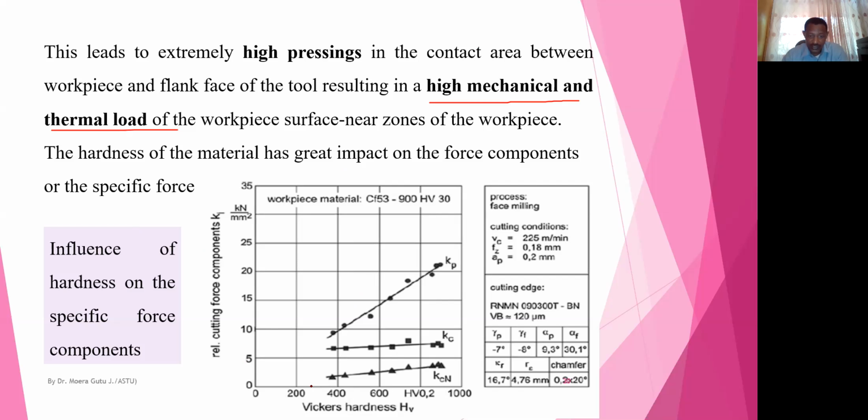So this is research conducted for different K value materials. K is the fracture toughness of the material. This is the Vickers hardness number. See here the cutting force component. The cutting force component here is very low for the ductile workpieces. We cannot really say ductile in hard materials, but for material which has low Vickers hardness, HV. So here the fracture toughness of the material is increasing as the hardness of the material reaches up to 1000 Vickers hardness number.